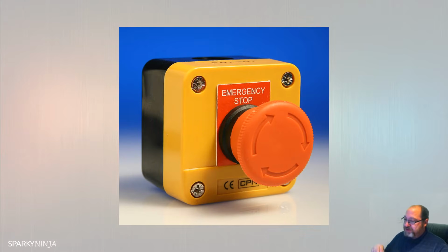And then we have emergency switching. Emergency switching is what it sounds like. It's removing the source of supply in a single action as we possibly can. These will be provided for any part of an installation where it may be necessary to control the supply to remove an unexpected danger. Where the risk of electric shock or other risk of electrical origin is involved, this emergency switching off shall cause the disconnection of all live conductors.